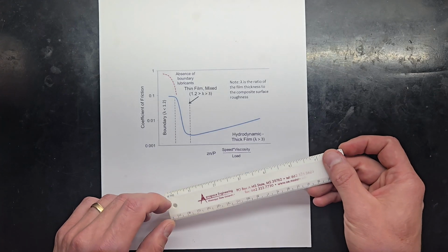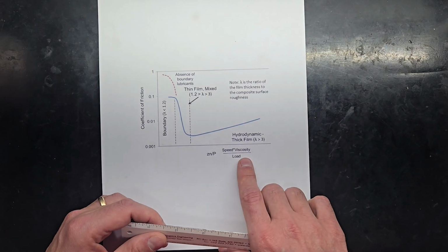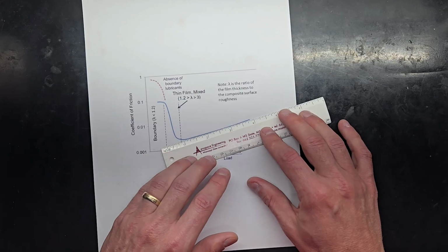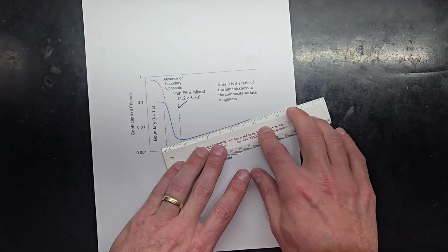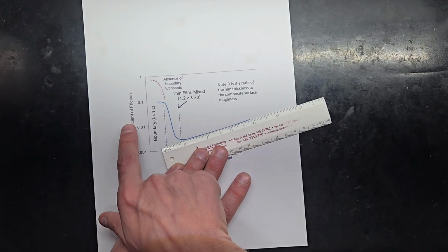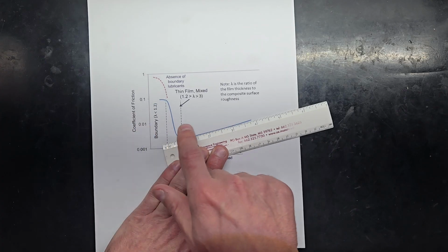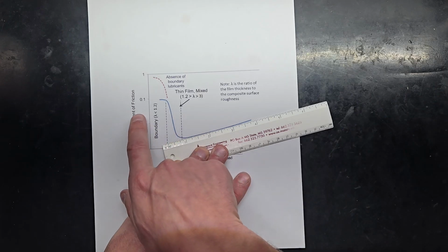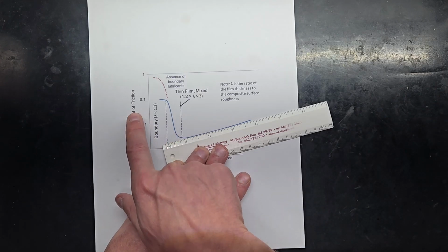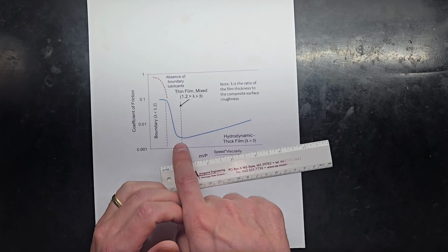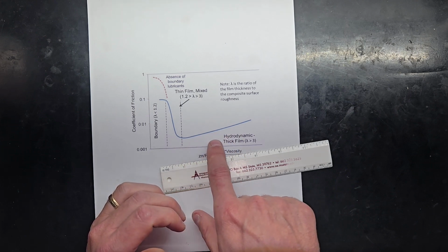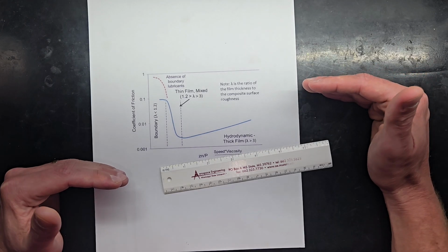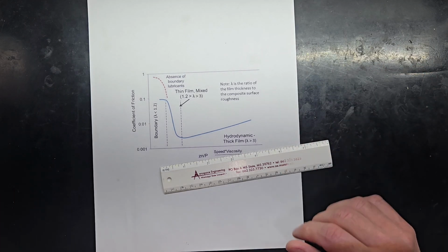And so in many things we think more is better, but we can extrapolate this curve and we can see we have friction, coefficient of friction on our y-axis. If you get too much viscosity, you also now start to increase your friction. So we want to find that balancing point of being low friction and fully hydrodynamic so that we get the best performance.